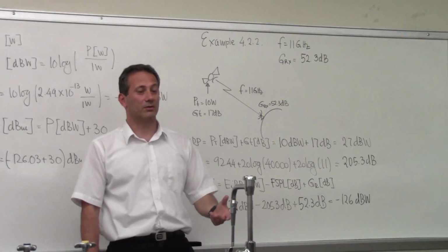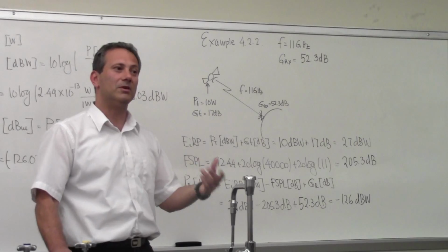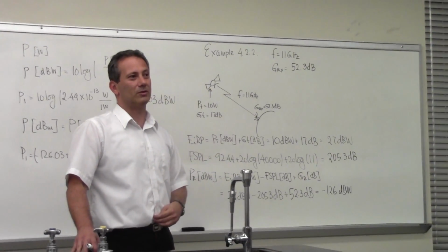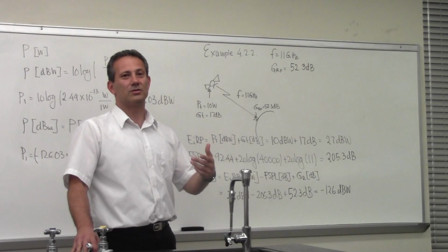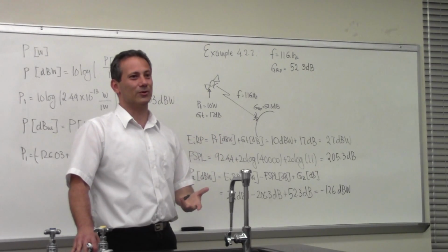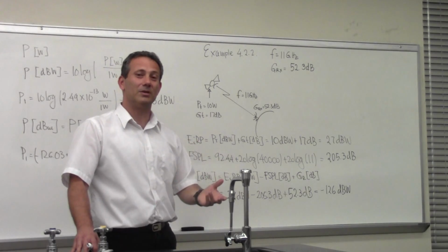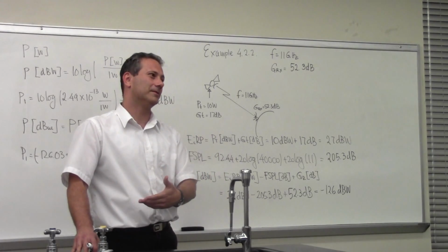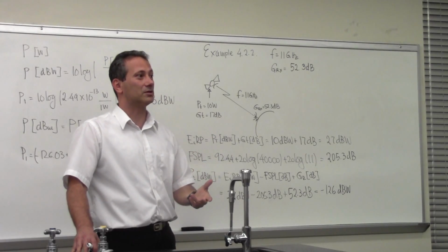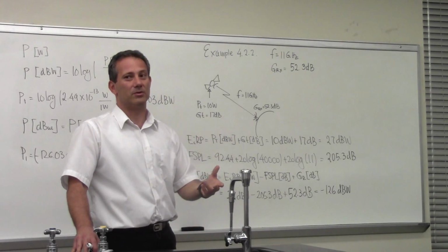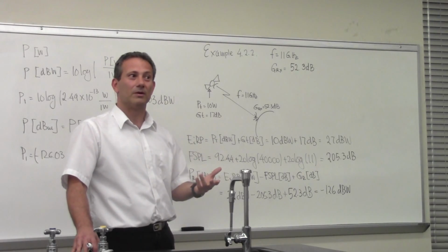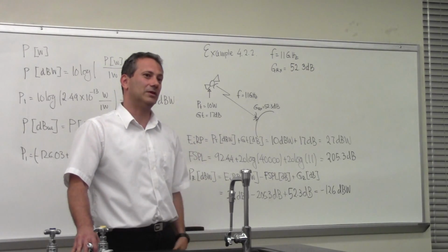It's extremely important, because if you start adding dBWs, it's not just, oh, I messed up, right? You don't really know what you're doing. You can subtract dBWs and the result is in what? In dB, and this is your signal to noise ratio calculation. But adding dBWs means you're squaring some power. And if you're squaring the power, you better have a good justification for doing it.